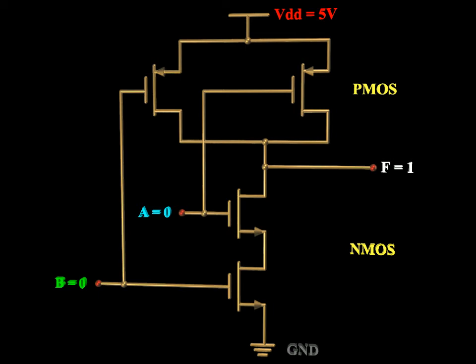The top two side-by-side transistors are p-channel metal oxide semiconductors. The transistor input is called the gate, and the other two legs are called source and drain. The direction of the arrows of the transistors show which type of transistor it is, PMOS or NMOS. And the legs with the arrows are the sources as opposed to the drains.